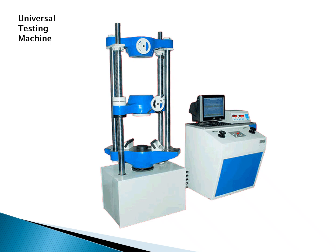Both stress and strain, and the material deformation properties, can be calculated using a machine called the universal testing machine. Simply put, the universal testing machine has two jaws, the upper and the lower jaw, to which any material sample can be attached. When a predetermined force is applied to this material, the computer next to the machine calculates the strain, and so we get the force per unit area, or the stress, built up in the material.